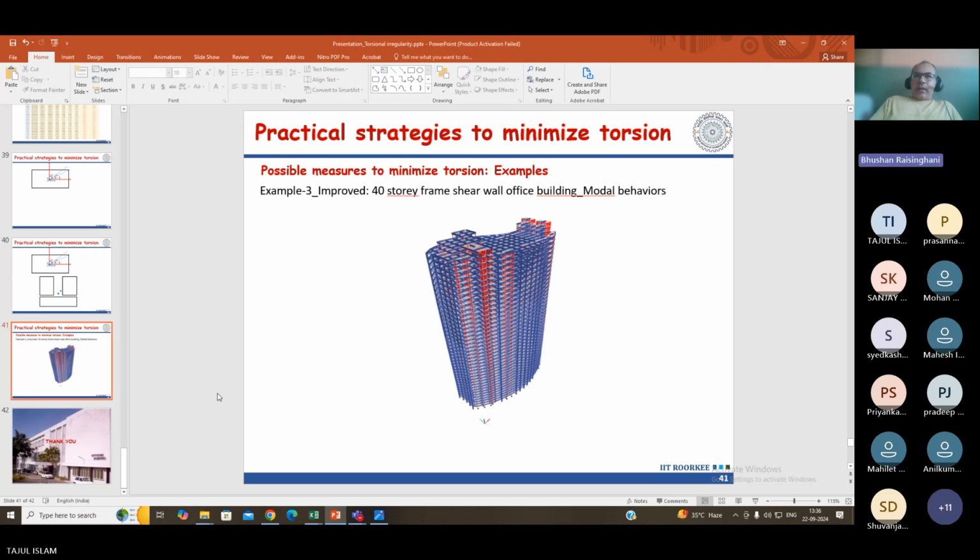So what you can do is take one column, take a portal frame, and apply a lateral force. Then in the same model, apply an eccentric force. In that you can check what moment change is happening in that same particular column. So with one single column or a portal frame, you can evaluate and check the design. That will give the final output basically.